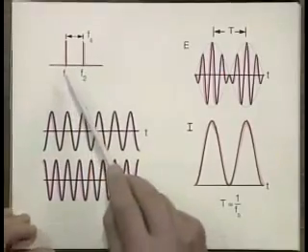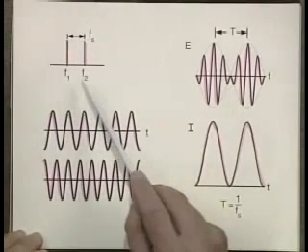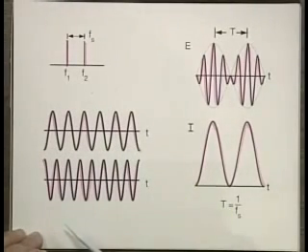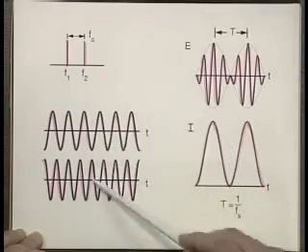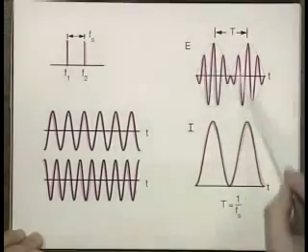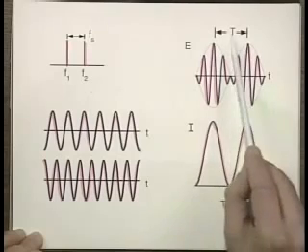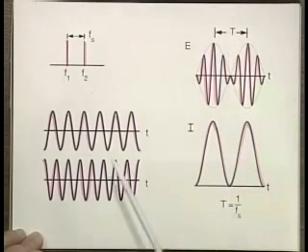But now let's see what happens to this constant output when I add another frequency. If I have two frequencies oscillating, one at f1, one at f2, here they are, with a difference in frequency, separated, let's say, by f sub s. Now, when I combine them and look at them in the time domain, I get something like this, which is a beat frequency. The period between these peaks, big T, is simply 1 over f sub s, the separation in frequency.